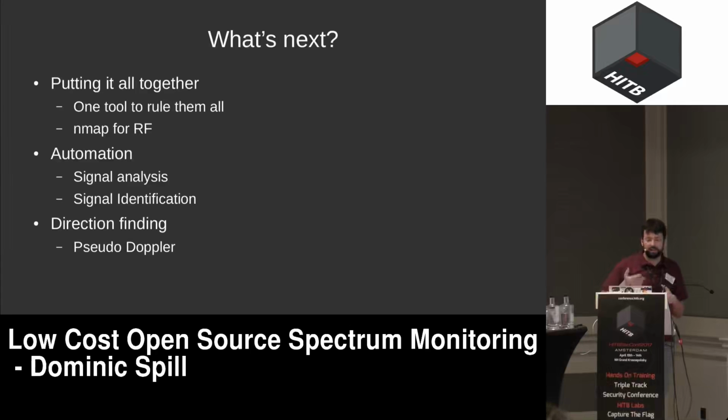Let's try and take a capture and dump it out to something like Inspectrum, where we can start playing around with processing it, filtering it, demodulating it, and so on. The other thing is we've recently been experimenting with an antenna switching board for HackRF that will allow us to switch up to 4 antennas on the front end from the firmware, which means we'll be able to perform pseudo-Doppler experiments using the same sort of techniques.